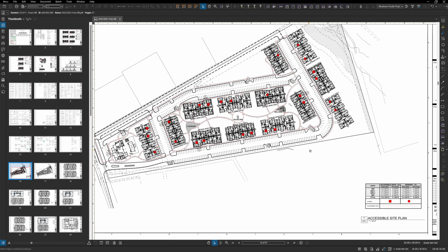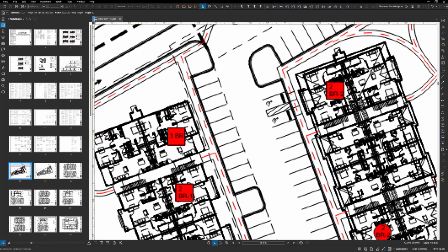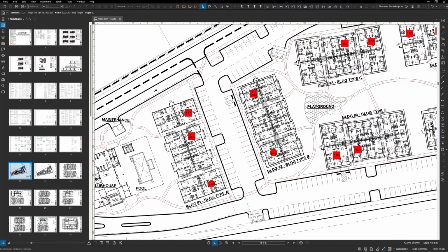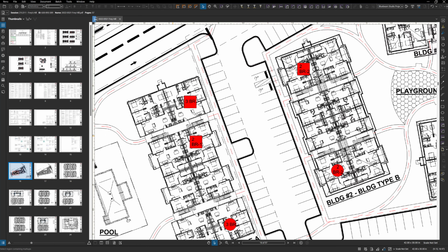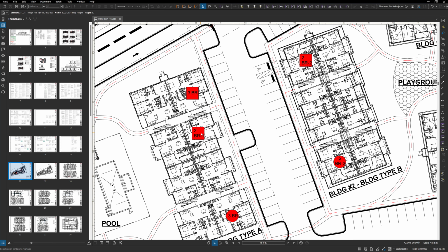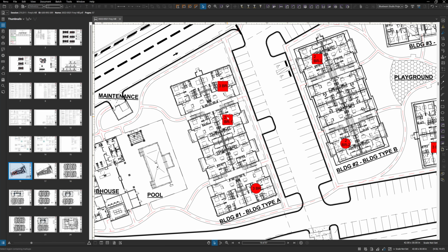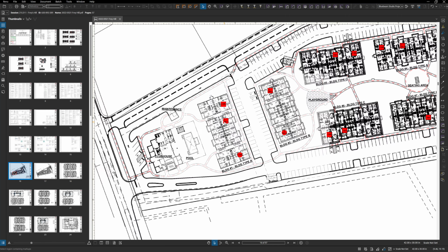So to map those out for the contractor, we provide a map of where we want the accessible units to go. Because for long reasons that I'm not going to get into here, I want to see a sidewalk to each side of the breezeway for an accessible unit. When you do these maps, I like to see the accessible units clustered together in groups. So this is a good example. This breezeway gets 1, 2. So I'm maximizing the fact that this breezeway has 2 sidewalks out of it that both need to be accessible, so I'm trying to pack them in there.